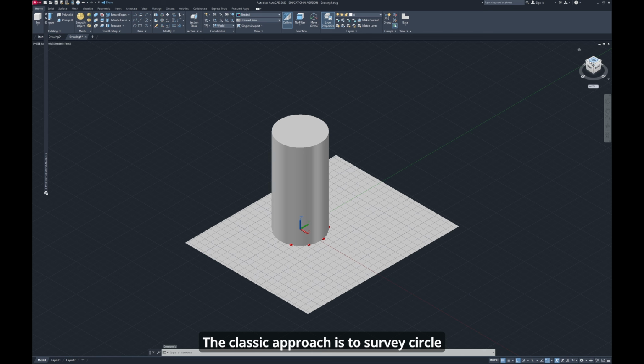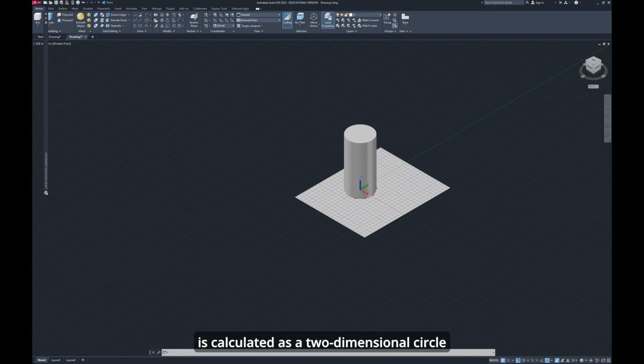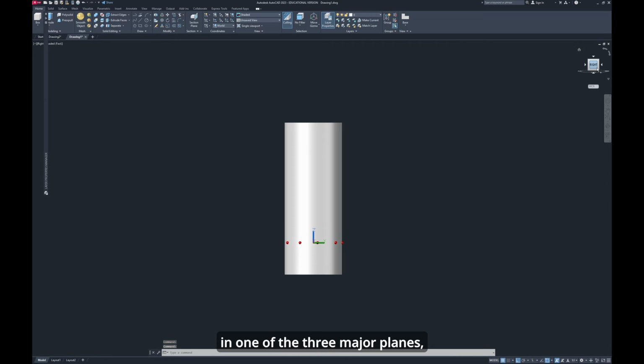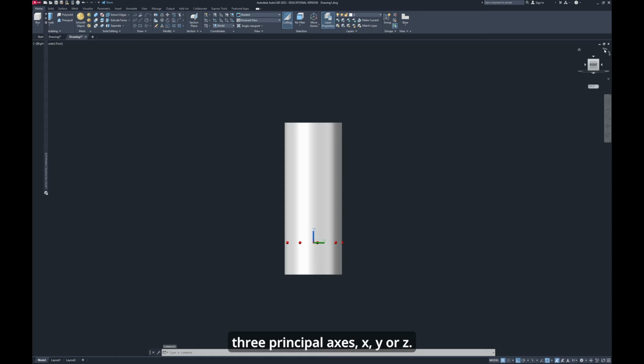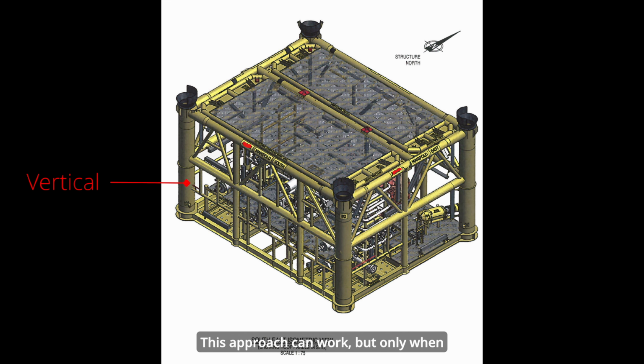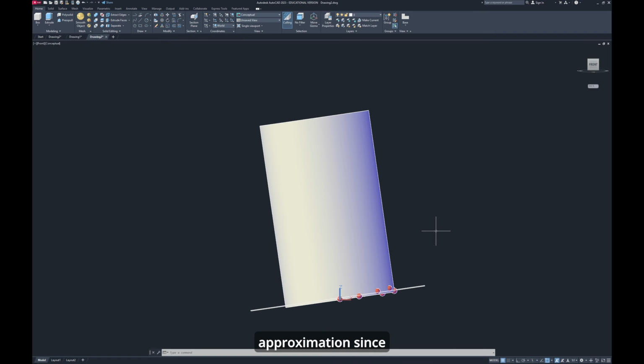The classic approach is to survey circle points by eye, attempting to position them in a plane perpendicular to the axis of the tubular. Then, during post-processing, the circle is calculated as a two-dimensional circle in one of the three major planes, XY, XZ, or YZ plane, assuming that the tubular's axis aligns with one of the three principal axes, X, Y, or Z. This approach can work, but only when surveying horizontal or vertical tubulars relative to the coordinate system. Even then, it's still just an approximation since inclination of the tubular is unknown.